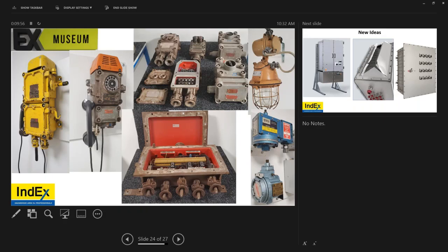Druckfest, pressure resistant. Thank you. Do you accept cable glands Class 1 Groups A, B, C, D into a zone application? The thing is, for North American glands, some of them don't even have that type of certification. No, I would not accept North American certified equipment meant for classes and divisions into a zone application.